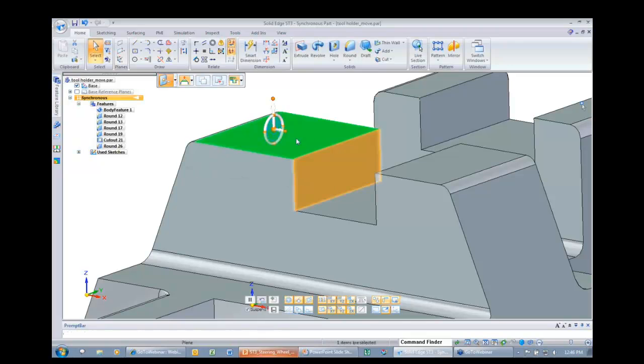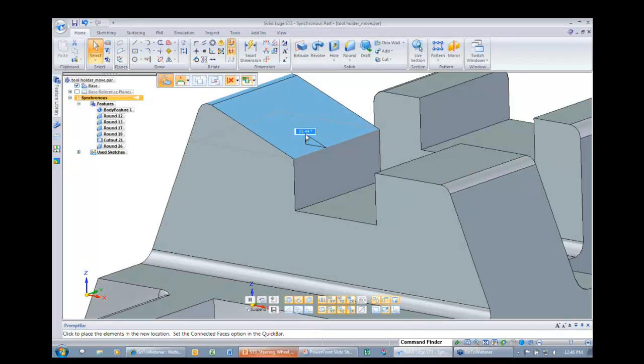So that's defining my 2. If I want to rotate this face, I can snap it over. Notice how the torus is normal to my select set. So just by clicking on the torus of the steering wheel, I can rotate that face.